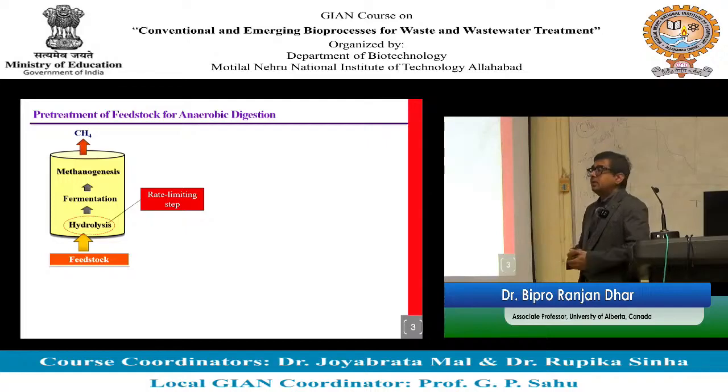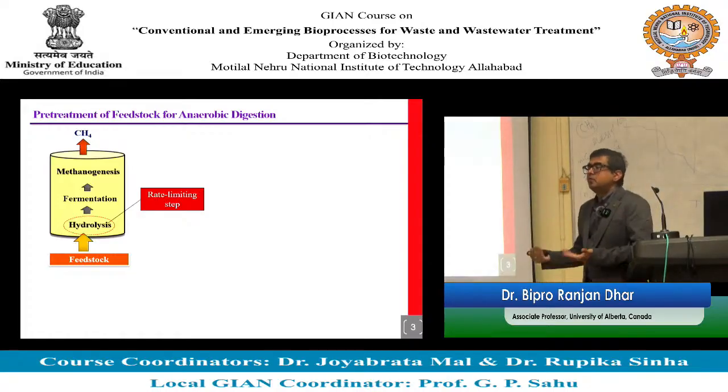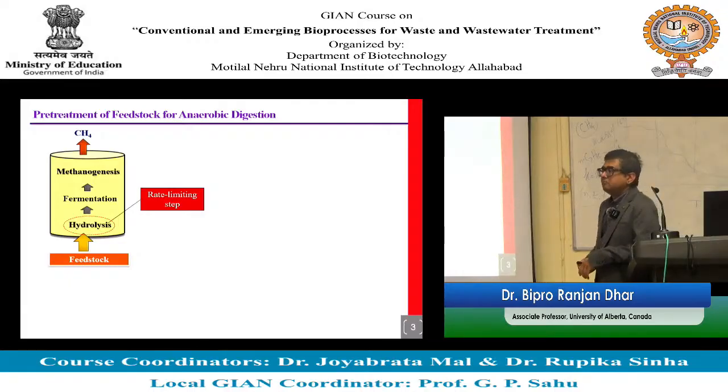For example, typical residence time for anaerobic digestion is 3 to 4 weeks, right? And in 3 to 4 weeks you might end up with 40 to 50% solid removal, which is not desirable. And if we provide more solid residence time or hydraulic residence time, it's also going to increase the digester footprint, and it's a big capital investment.